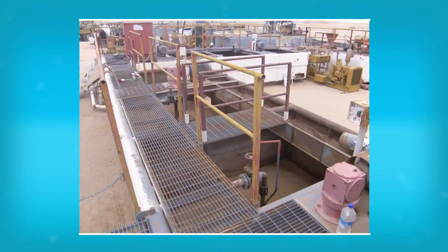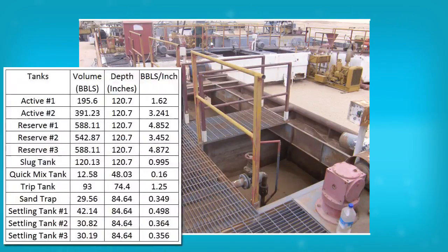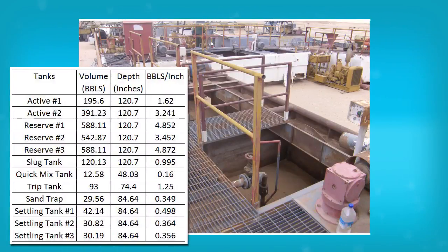Drilling fluid starts out at the mud pits. The mud pits are a series of tanks where the drilling fluid is stored. During drilling operations, one or more pits are assigned as the active mud pit. The active pit is monitored to ensure the correct amount of fluid is returning. Chemical checks are done on the returned fluid, as well as the physical checks to ensure that the density and viscosity are correct. Using the active pit gives a closed system which makes it easier to monitor.